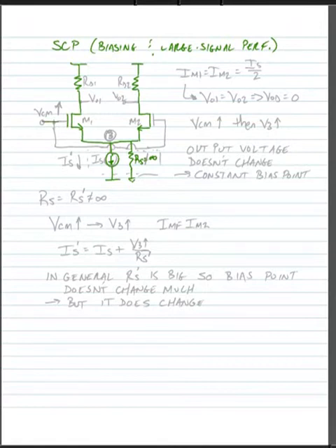And we're going to look at this with a common mode voltage. And what common mode voltage means is we're going to put an input voltage that's tied to both terminals. In other words, it's common to both inputs of the differential pair. And looking at the output on both drains of this differential pair.